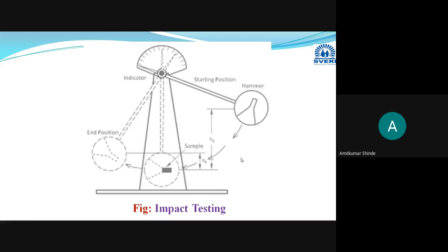It is the energy absorbed by that particular material or test specimen, and here impact is also there, and as the specimen is fixed in the form of a cantilever beam, at the free end, due to the impact from that hammer, tension is also created. That's why the amount of energy absorbed by that particular test specimen before the failure will be termed as tensile impact energy.